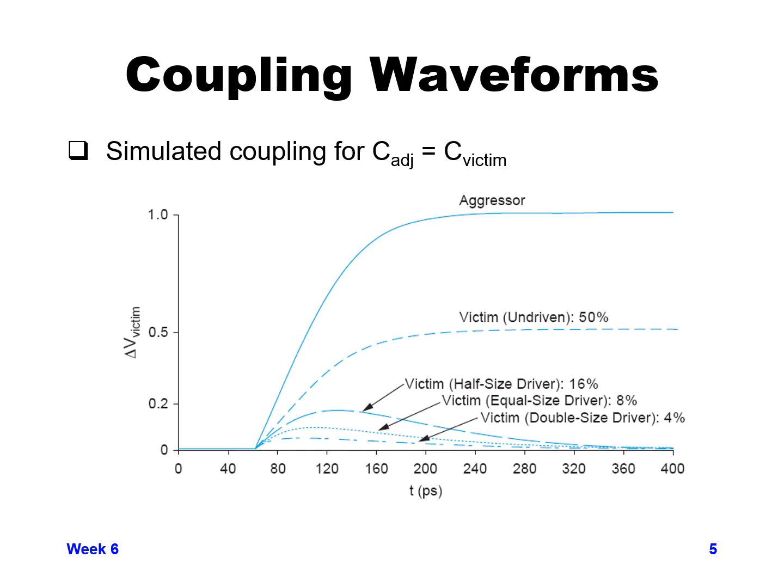We could see a doubling of this voltage value potentially. So you can see there could be occasions where you have a really strong aggressor and maybe a really weak victim and have multiple attackers on either side and possibly even attackers above and below in the wire layers, one layer above and one layer below, that could all cause potential noise on a given victim and cause a potentially significant amount of noise depending on the situation.